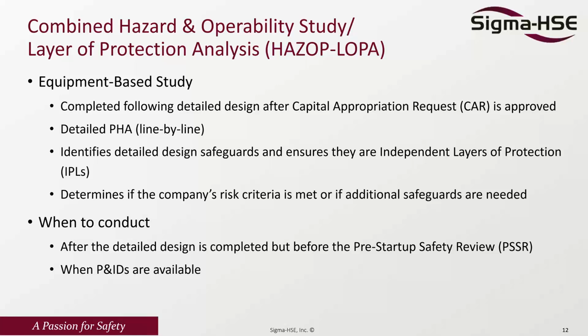We conduct the HAZOP after the detailed design is completed, but before the pre-startup safety review. So now we're in the construction phase of the project, and P&IDs must be available to complete the HAZOP.